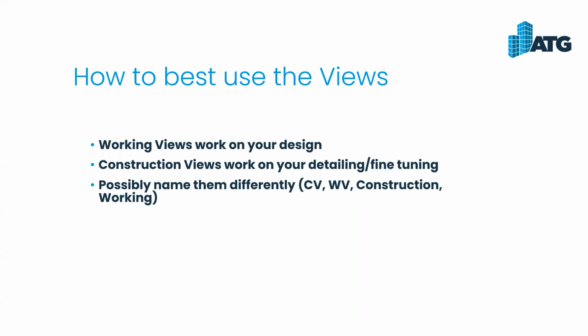Also, what some people will do is name them a bit differently, because you could have a 1-HVAC plan in working, and you could have a 1-HVAC plan in construction. What you can do is put maybe a dash CV for construction view, or WV for working view, or just simply construction or working on the back end of that. That's an option that you have.